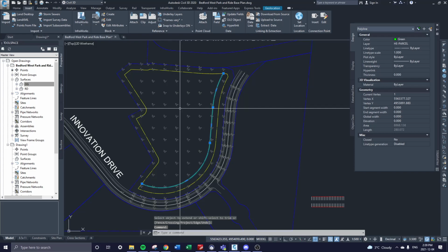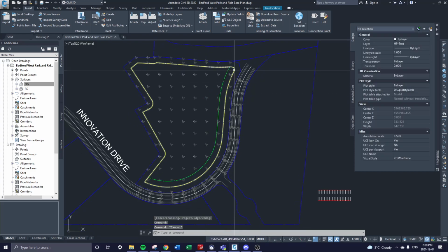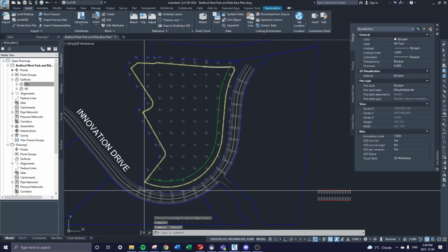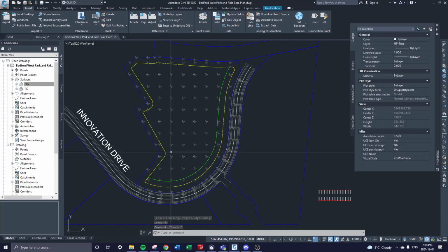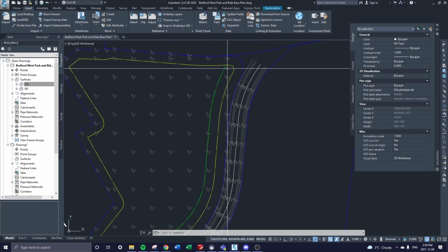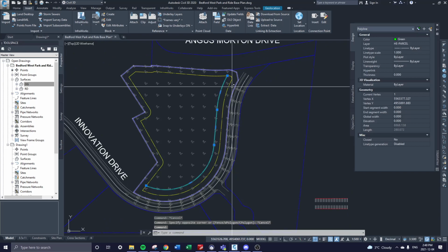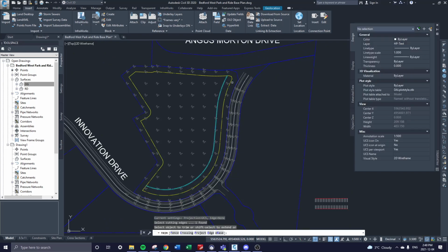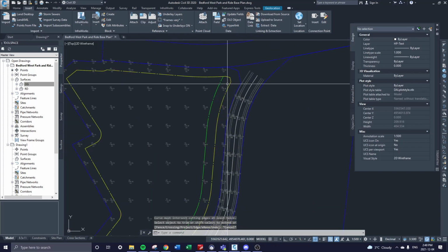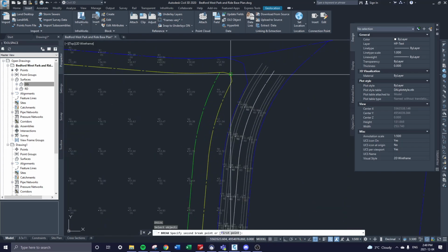Terrific. And then the new boundary, now we don't need this yellow line, right? Because this is the green line that governs there. The yellow governs everywhere else. So what we're going to do is select that green line, and we're going to trim. Oh, okay. I guess it doesn't want to trim. Sometimes you'll have to break it instead.